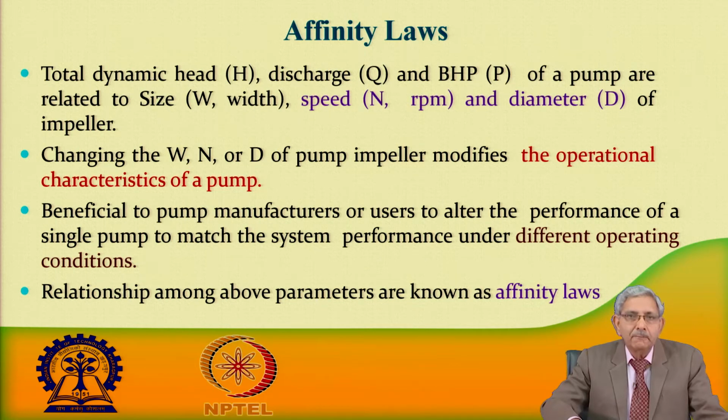They are interrelated, and by changing these parameters, the operational characteristics of the pump also change. These are beneficial when we understand them fully, to alter the performance of a single pump to match the system performance under different operating conditions.